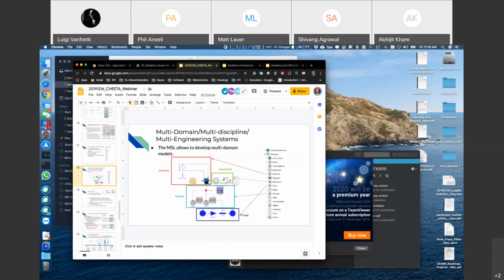And here you have the ambient temperature. This circuit here is the thermal network for that motor. So for that component, we can establish a thermal network model. And at the bottom, this is the cooling circuit that is going to cool the thermal network and change the temperature on the motor.